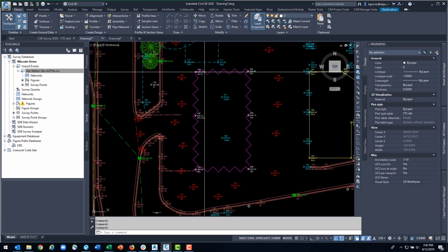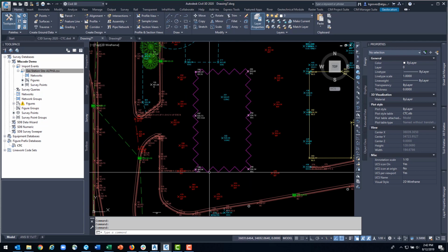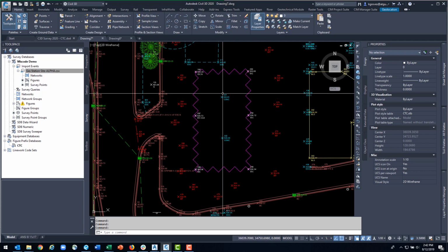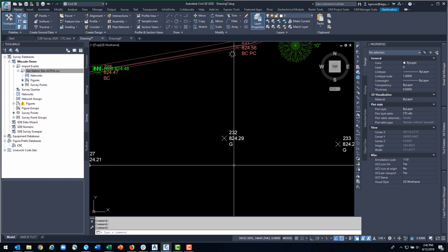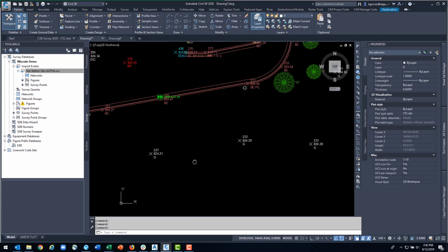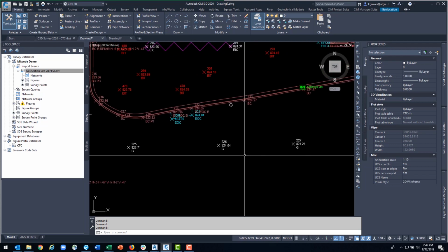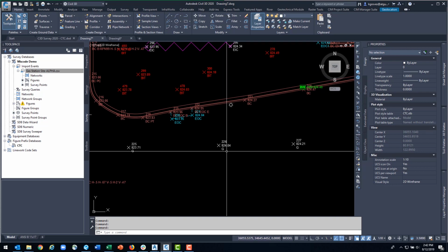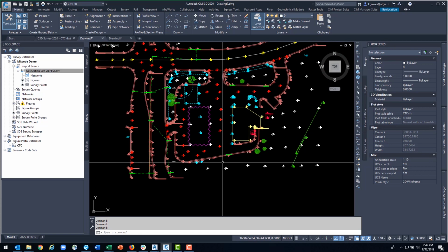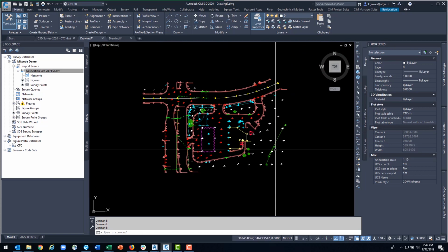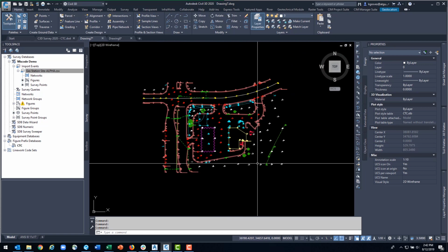Because this is creating a survey figure for me, I've already got that Miscode survey figure style set up, but what about our survey Miscode for our ground shots? Now, again, I know that this is a Miscode across the board because at my firm, we use GS, not just regular G. So again, someone was either feeling lazy or looking at the wrong code sheet that day. But these aren't immediately obvious to me as miscodes.